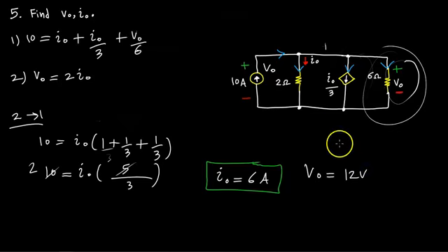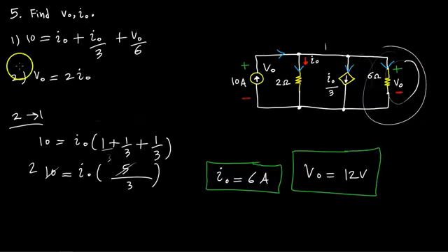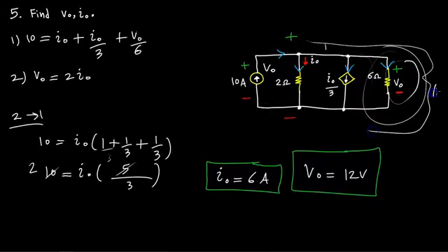Now, since we've already come this way, let's just go ahead and find the power dissipated or absorbed by or sourced by each element. So V0 is a positive quantity, which matches with this convention. So the voltage applied across this circuit is going to be a whole 12 volts. Let me just write it. 12 volts here is applied, and the current is also positive, so I0 is going in this direction, indeed.